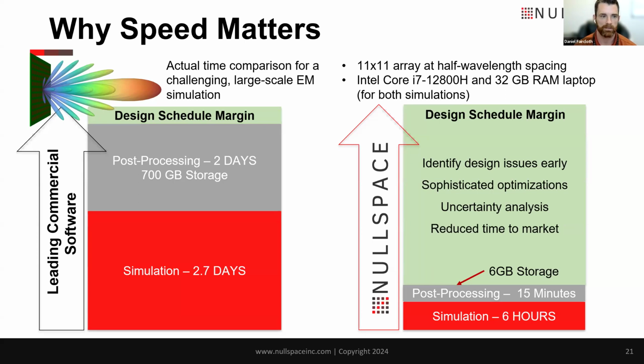This is an 11 by 11 array with dual feed patch antennas. So the idea behind the simulation is you want to synthesize the embedded element pattern for every one of the feeds involved in this array, and using that data then do weighted superposition of those patterns to yield a full array beam pattern. And then you can do optimization and beam weighting adjustment to study beam steering, and maybe get beam steering error or max gain roll off, and those important metrics in designing a phased array.